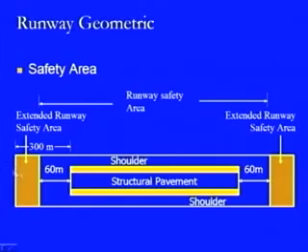The length of this safety area will be at the maximum of around 240 meters, as the final distance of this safety area with respect to the end of the runway strip is 300 meters. So, this is the overall normal safety area being provided in this case, and then it is further extended, so that this becomes the total safety area which will be available for the movement of aircrafts, looking at the emergencies which may be caused.